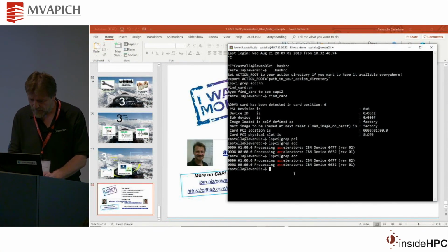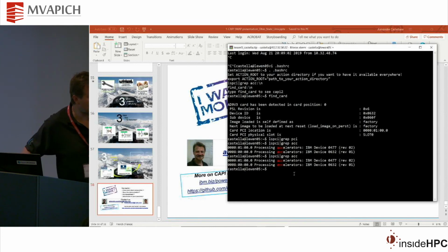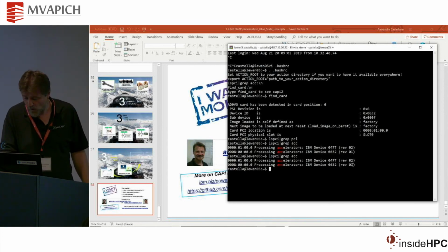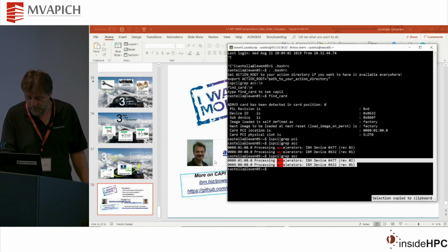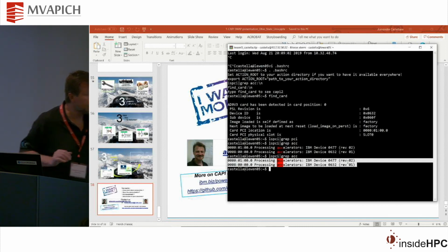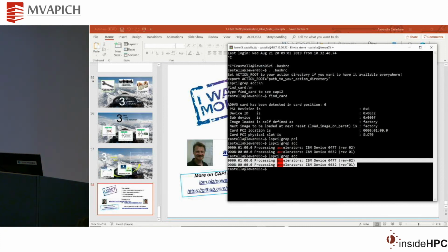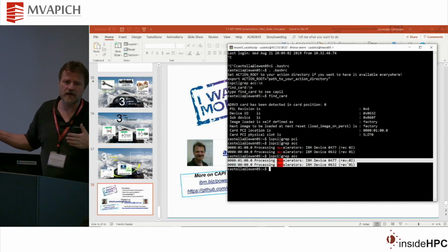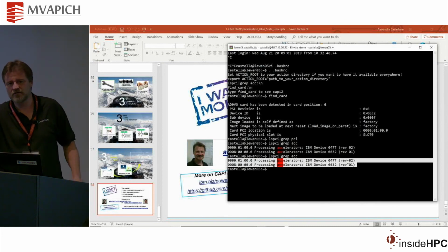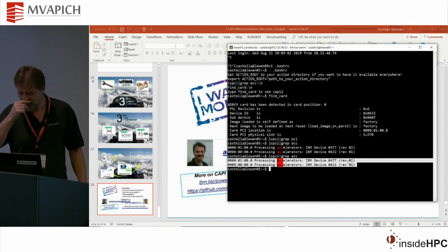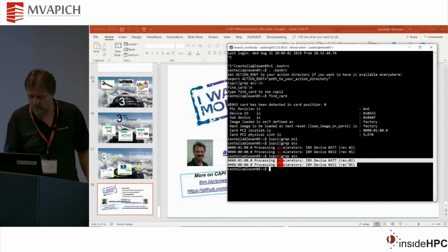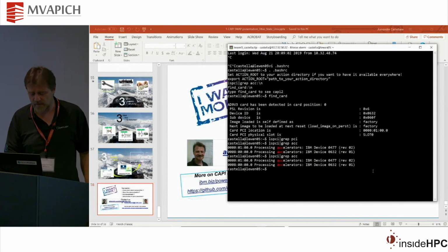Okay, so here, if I run lspci and ask what accelerator it found in the system, it says it found one, and this was the initial kernel discovery. It created for me a virtual port, which is not a PCI Express port, but it's treated as if it is organized and sorted in the same area as PCI Express. But this makes sure that I have an acceleration available in CAPI 2 mode.